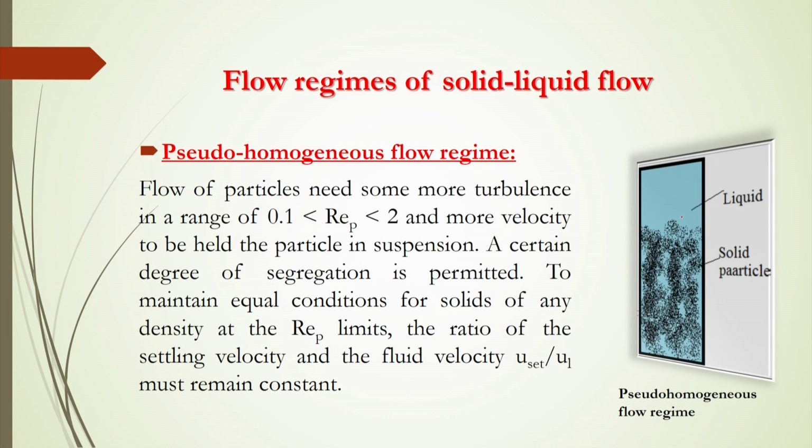So, this is the pseudo solid-liquid flow seen in this picture. Here there will not actually be a uniform concentration inside the bed, because there will be some voidage distributed inside the column that is not uniform throughout, and particles may also be agglomerated inside the bed.